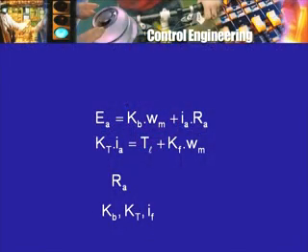Now here again you can see roughly what is going to happen if Kb and Kt are less than what was assumed, because, let us say, the field current has decreased. If the load torque remains the same, then the torque equation, the mechanical equation, tells you TL is the same. For the moment, assuming omega m is the same, Kt Ia has to remain the same, but Kt has decreased, so Ia will increase. The armature current will increase, so the armature drop will increase, so the back EMF available will decrease. In addition, Kb has decreased, so omega m, what is going to happen?